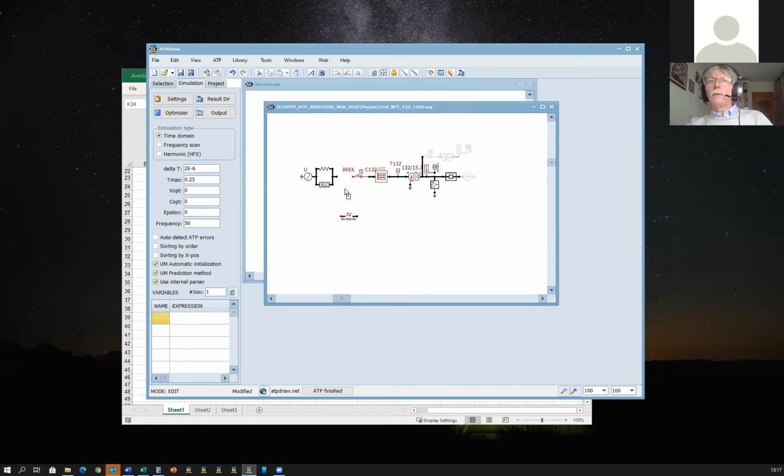When you disconnect from the source, even if you use the hybrid model there and the nonlinear core is represented as a hysteretic model, the residual flux could be represented this way, because the residual flux is not input data, but it is set by the system when you de-energize the transformer from the grid. If that was the question, how to represent it.